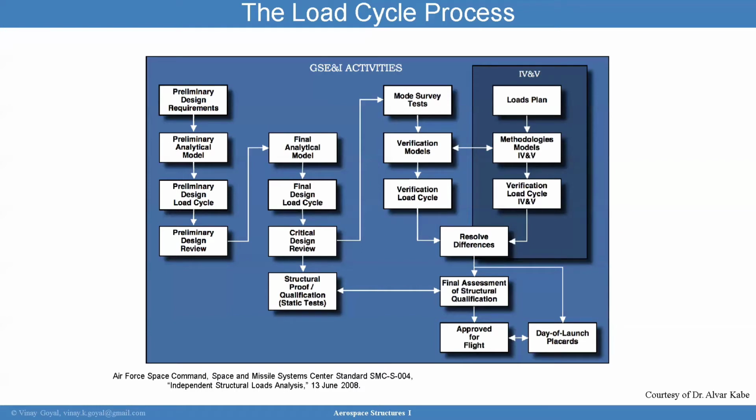You need to make sure that the launch vehicle model and spacecraft models are adequately anchored dynamically. Otherwise, you're going to have error in the predictions. Also, models usually do really well with the first two global bending modes. The fundamental axial mode tends to be less certain, and the fundamental torsion mode is usually even less certain because of the complexities of modeling torsion.